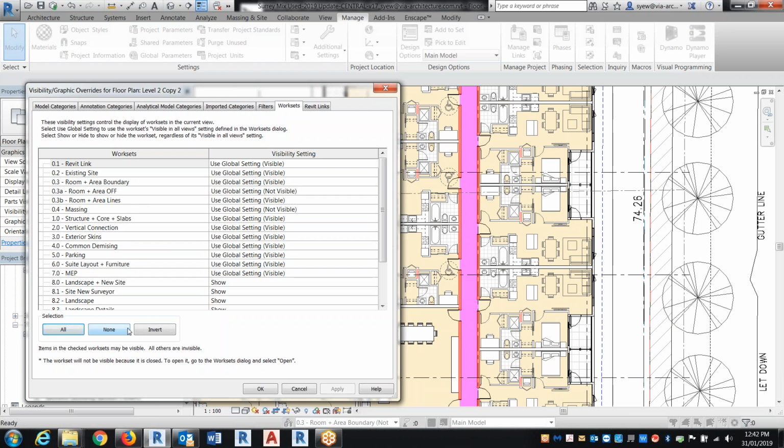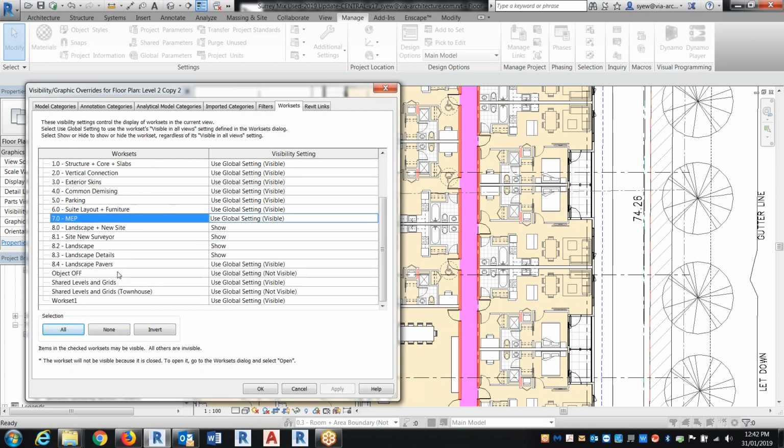So you don't open the whole model, you only open up that small model. This is why I'm always very, very adamant that people, if you're working on larger projects, always put in a workset, because when the project gets too big, sometimes you run out of memory very fast. So the only way you could do it is to open up your model partially so you don't open up everything.